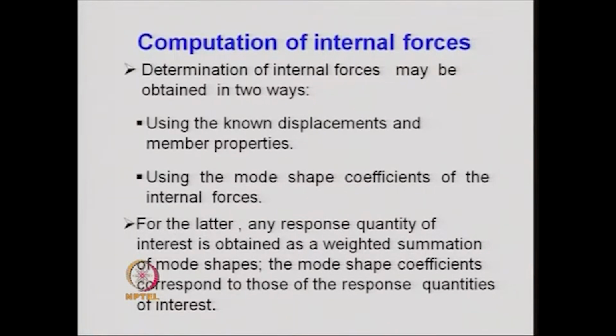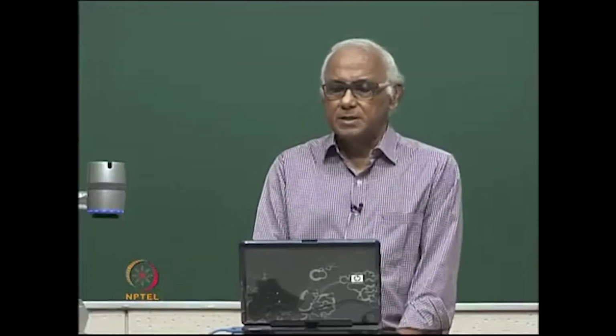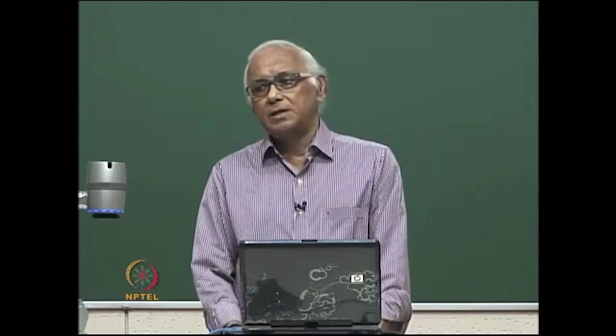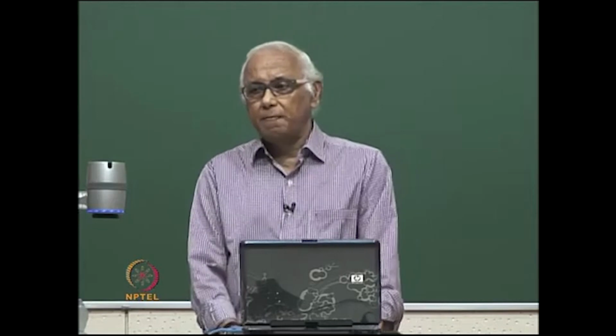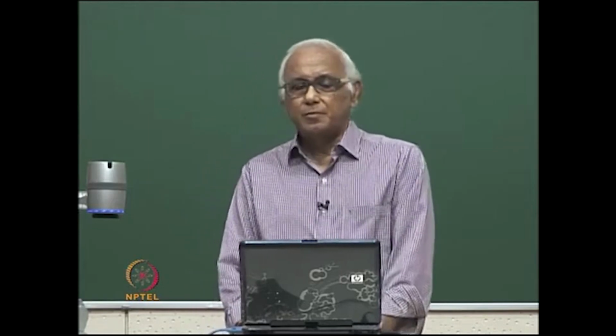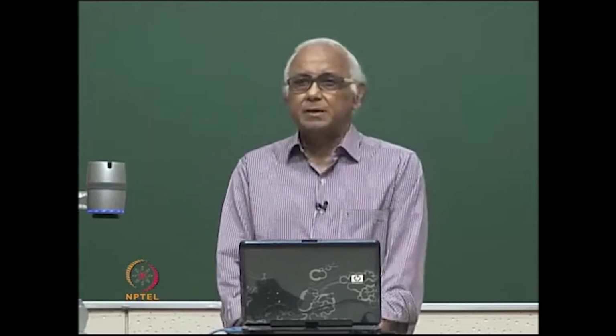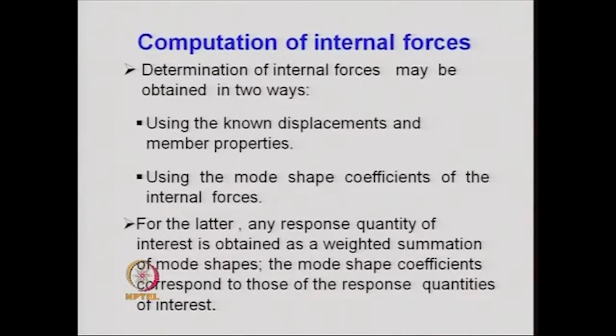In finding out the displacement responses, we can use either the mode acceleration approach or the classical modal analysis. In classical modal analysis, the number of modes to be considered is obtained from the mass participation factor, but that guideline is valid for the displacement response.